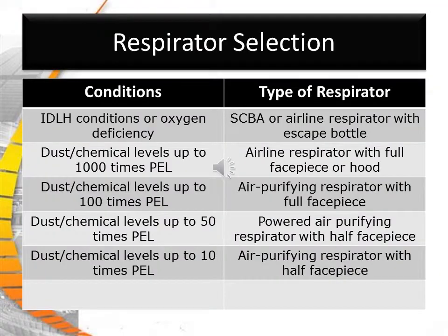Conditions and types of respirators. IDLH conditions of oxygen deficiency require SCBA, while dust and chemical levels up to 10 times the PEL require an air purifying respirator with a half face piece.